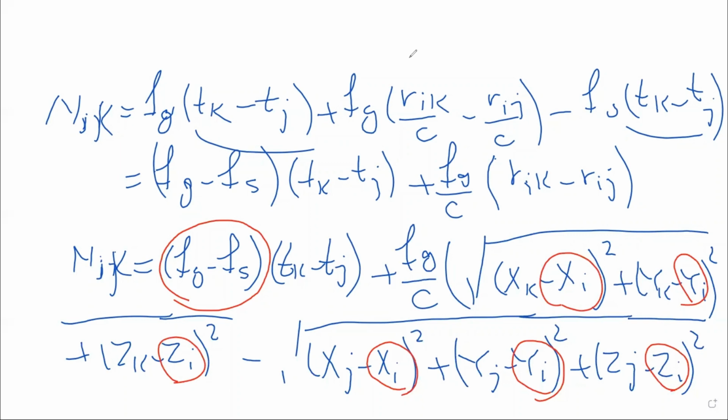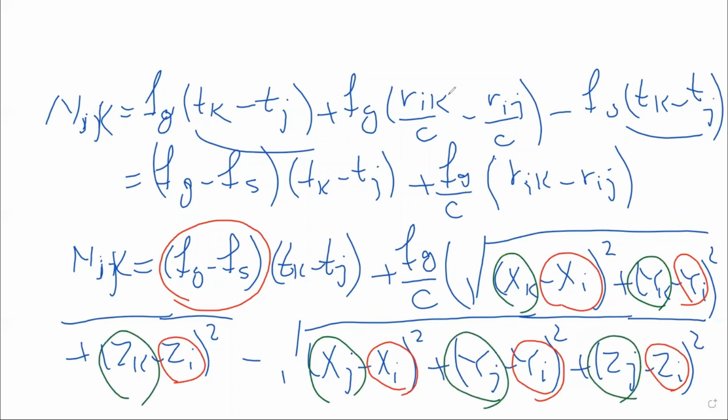The coordinates of the satellites are now known at two positions, and this term will be constant because we have only one source and one receiver, so it can be estimated. And the Doppler count actually is the observed measurement.